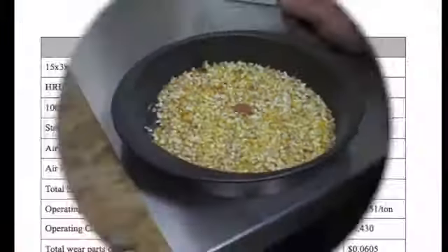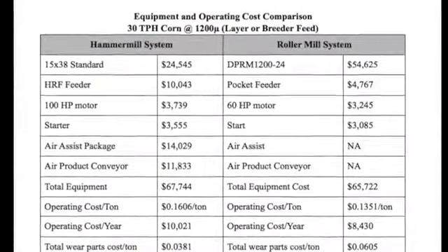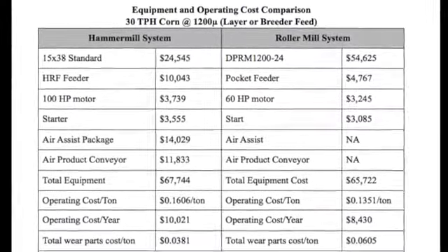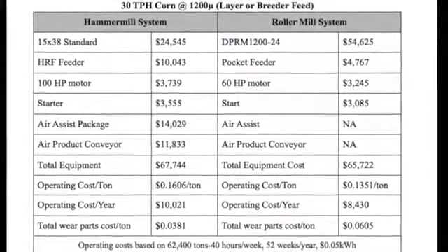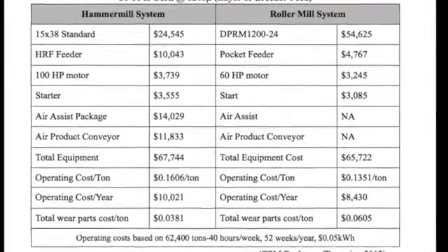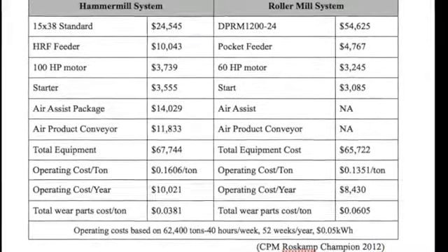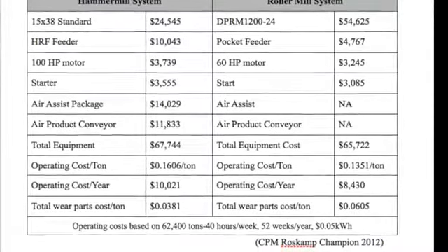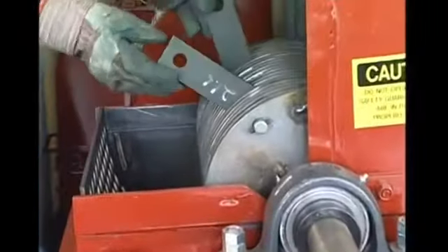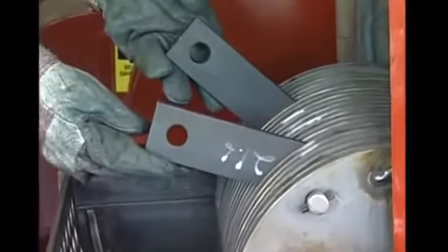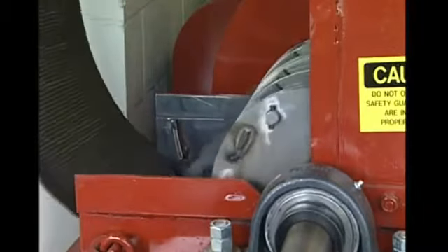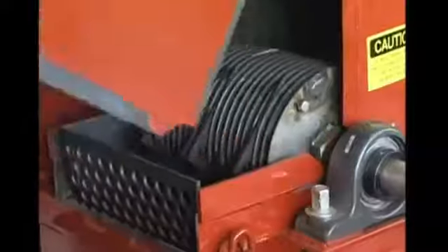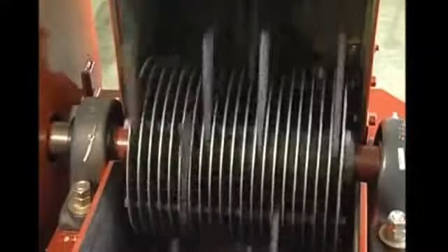An estimated cost for installation of a hammer mill and roller mill are roughly 2 times the cost of the equipment itself, according to Dr. Charles Stark. So in this case, the installation cost would be approximately $135,488 for the hammer mill and $131,444 for the roller mill. It costs less to install and operate a roller mill due to the savings in energy. However, a hammer mill makes up for its higher energy cost with its ease of operation and inexpensive and easy maintenance. Facilities want a hammer mill because if something breaks, they can reduce the amount of downtime because it is quick and easy to fix.